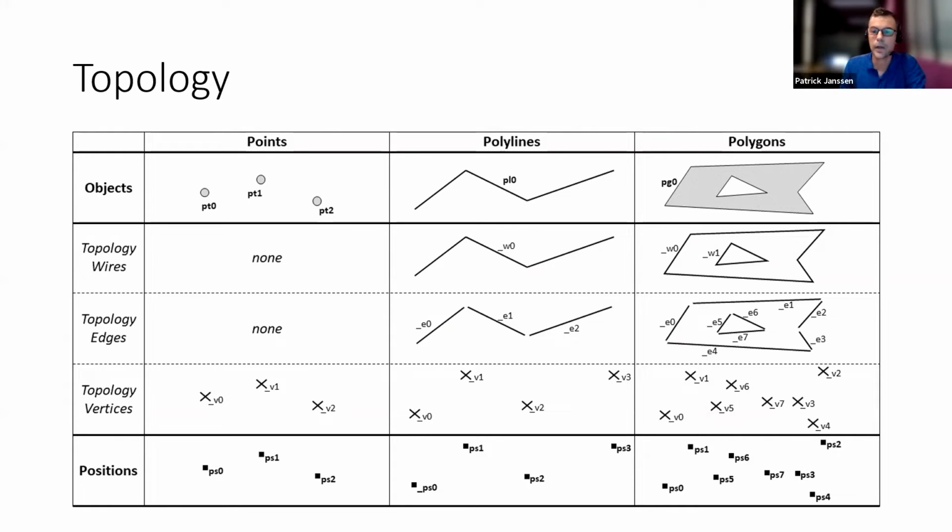For example, if you look at this polygon, you can add an attribute to the hole. You can say what this hole is: this hole's a window, or this hole's a void, or it's something else. You can add information to your model that describes what everything is. Another common thing in urban modeling is that you have a polygon that represents a plot, and you want to know which side of your plot is facing the road and which side is facing the back. So you add an attribute to the edge, and you say this edge is facing the road.